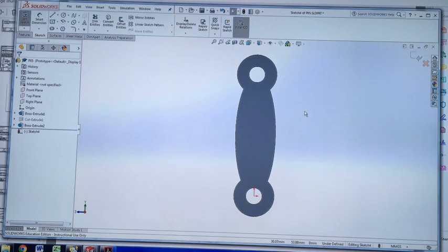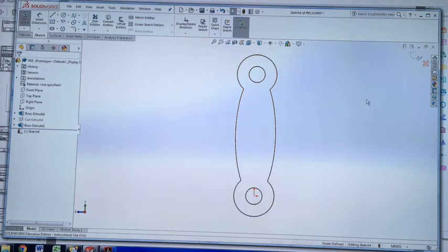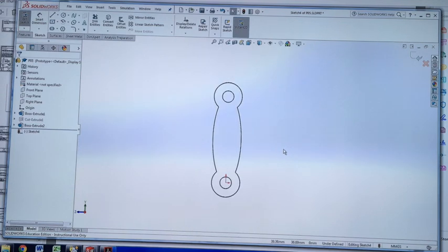In SolidWorks in 3D, you can make it look one of three ways. You could do the text like we did before with the manufacturing with an engrave that just goes 0.2 of a millimeter down, or you can cut all the way through, or you can cut a different thickness entirely. What you need to remember or start to think about, and we'll talk more about this later, is when we export this file, all we're exporting is 2D geometry, okay, for the laser cutter, which means it doesn't read any depth whatsoever. All it's looking at is this top view of the part to see where the lines are.